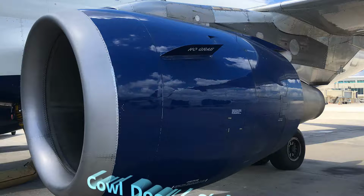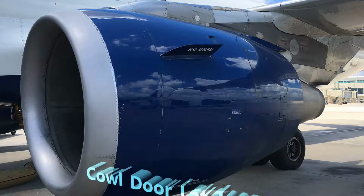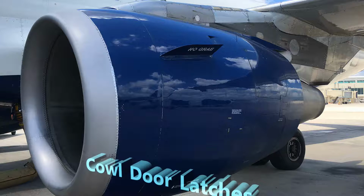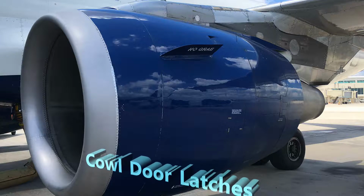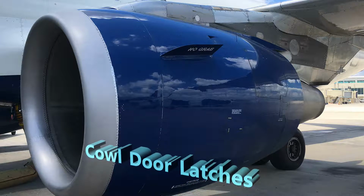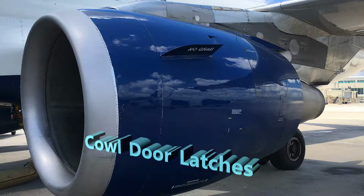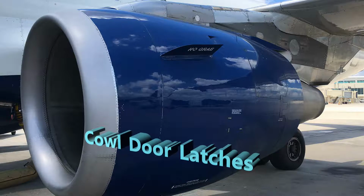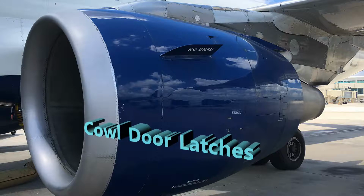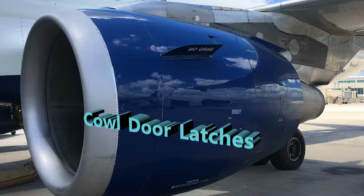All right, let's talk about latches. There's a lot of latches, and you're not going to be memorizing any of this, by the way, but just to heighten your awareness about the latches and the mechanism for unlatching the latches and closing them as well. And there's some protective devices as part of that in case you forget to latch one completely down, for example, after you've accessed through the access panel. So right here on the fan cowl, there is a latch access panel that's going to give you access to the latches when you're wanting to open those fan cowls.